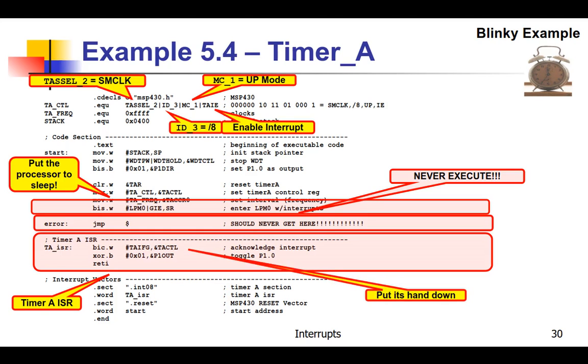And notice that in the interrupt service routine you have to clear the interrupt flag. Otherwise it'll keep coming back to this ISR.